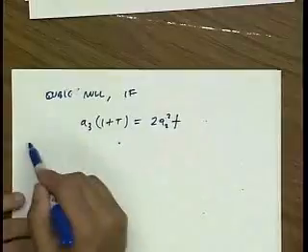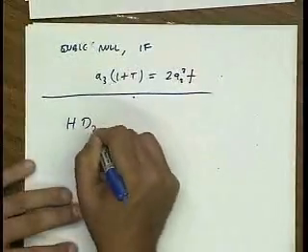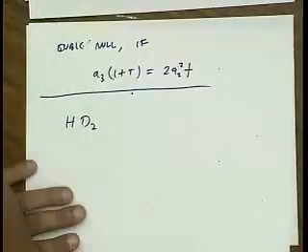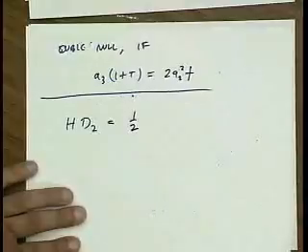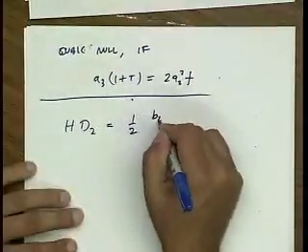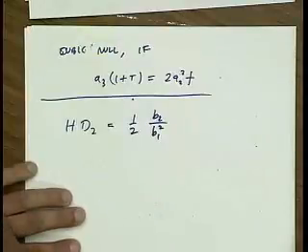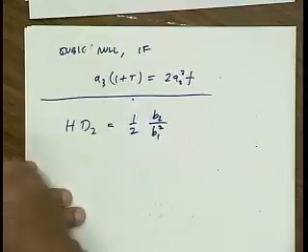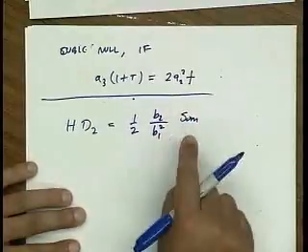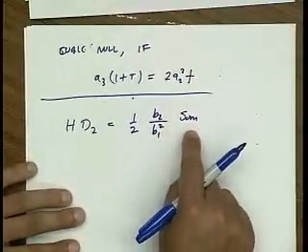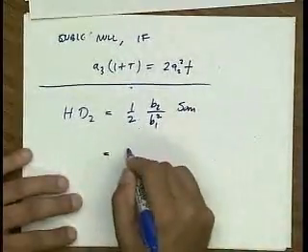All right, so now that we've derived these equations, we can plug the results into all the important metrics. For instance, if I'm interested in second harmonic distortion, the equation I derived a couple of lectures ago relates it to b2 over b1 squared for a given output signal. It's very important that I compare the same output signal, and I'll come back to that in a moment.